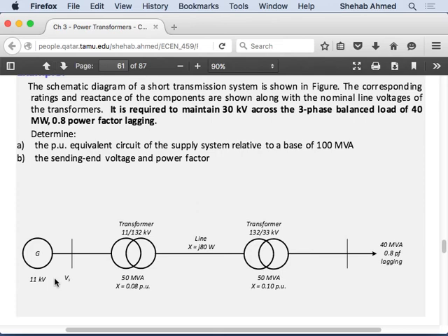So they're telling you about the receiving end, which is my load. Then it's a circuits problem now, like chapter 2, right? What we've done now is reduce this chapter 3 problem, a bigger power system with transformer ratings and so on, to what we have in chapter 2. So now they go back and add the same complications that we had in chapter 2: draw power triangles, look at power factors and stuff like that.